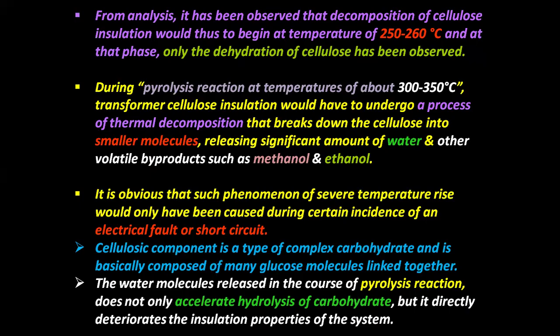It is obvious that such severe temperature rise would only be caused during incidents of an electrical fault or short circuit. Cellulosic component is a type of complex carbohydrate and is composed of many glucose molecules linked together. The water molecules released in the course of the pyrolysis reaction not only accelerate hydrolysis of carbohydrate, but also directly deteriorate the insulation properties of the system.